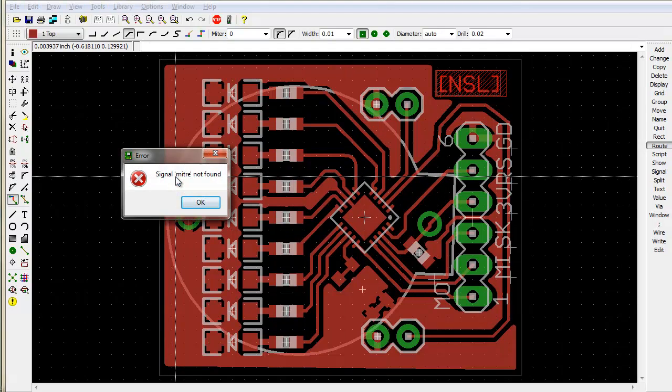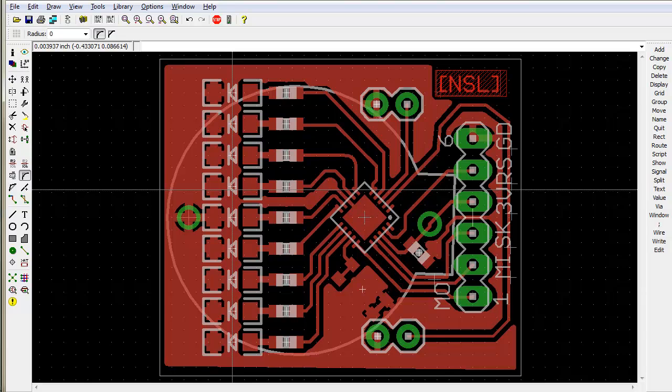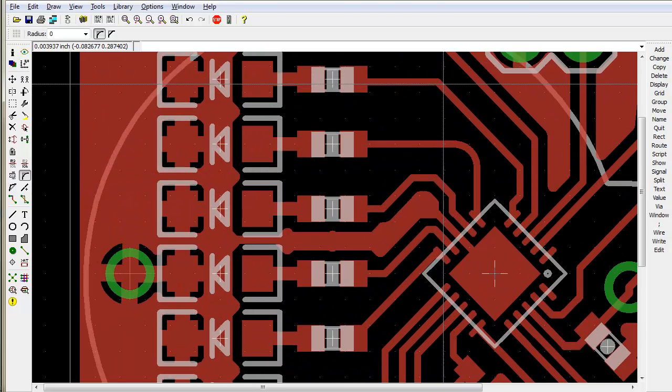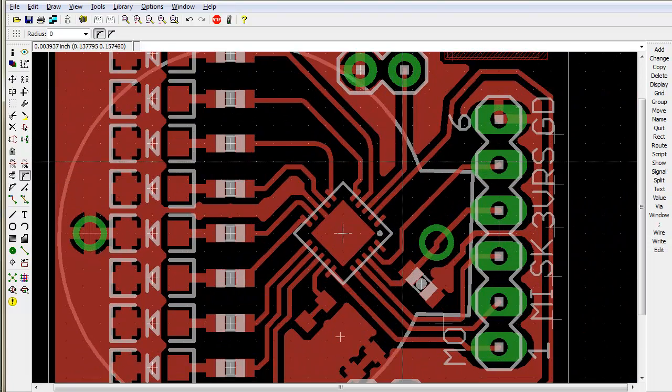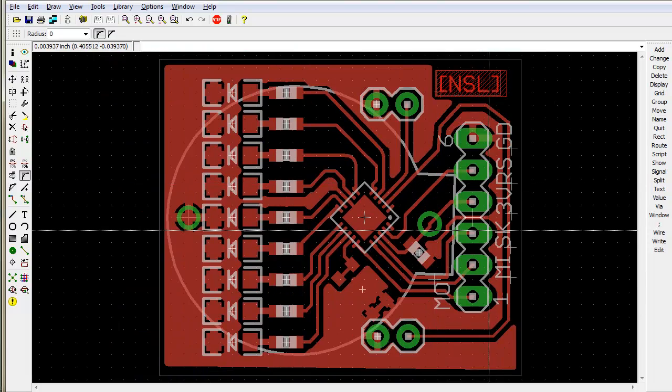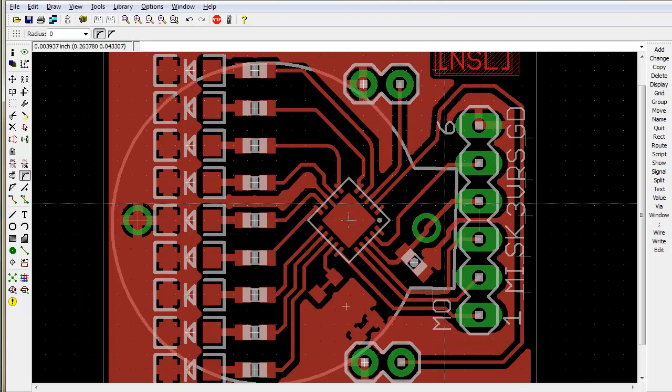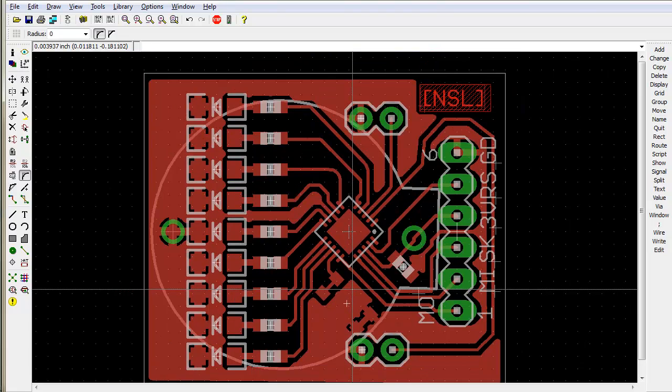We show the miter command, I think we talked about before. Miter, spelled correctly. What that does is allow us to put little bends and be all artistic about it and make it look pretty. That's one of the things about PCB design. A lot of people do spend a lot of time making it look pretty. You shouldn't. Make it work. You can spend way too much time routing a board and filling in all the little tiny details. If it passes DRC, if it's electrically correct, that's all you really need it to be.